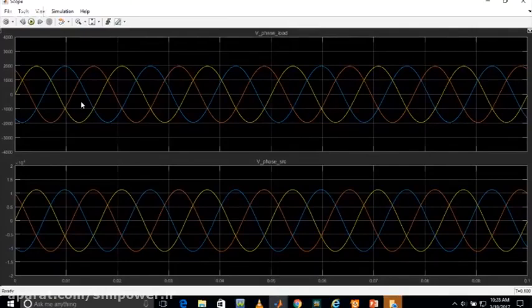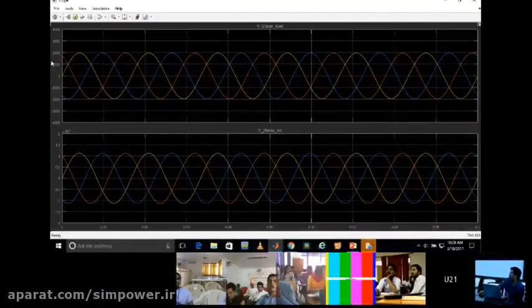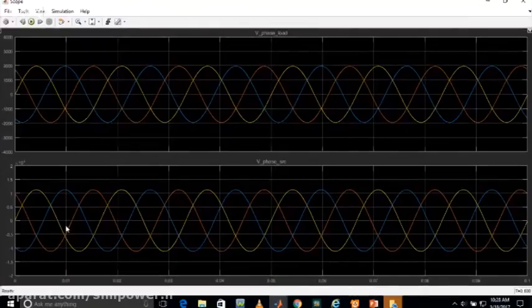So a little bit of voltage will be wasted there, and our RLC load will have up to 2000 volt maximum. And this is the three-phase source voltage, which is up to, as we already know, 13,800 volt. So as we can see, this is how to connect a three-phase RLC load which has a different voltage parameter to the three-phase source using a linear transformer.